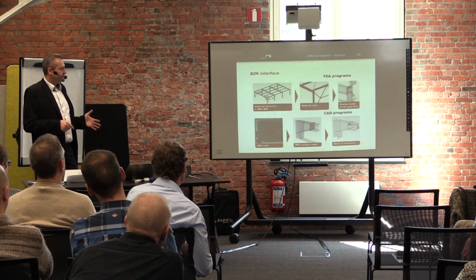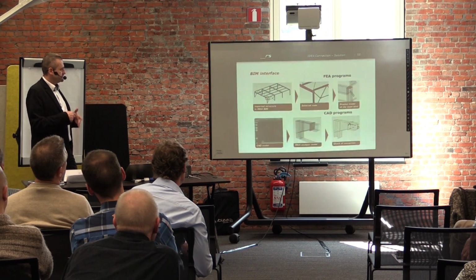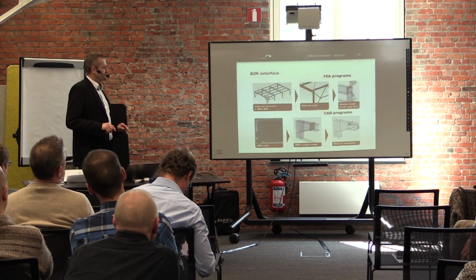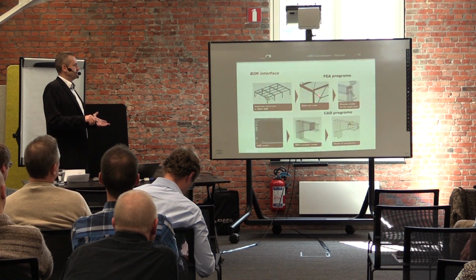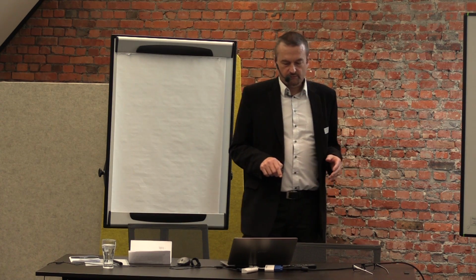On this example, we are able to read the shape of the structure from a finite element program. But we do not calculate it. We have the shape and we have internal forces calculated by somebody else. In case of connections, we say I want to design the connection in this node, and from that we generate the model directly in IDEA Connection, and you can make a proper design of this node.